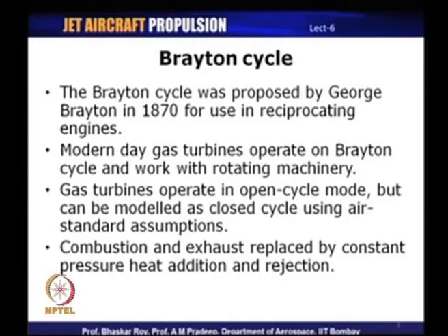That is, we assume that the combustion products can also be modeled as air, and so using that assumption we can still continue to use the Brayton cycle analysis for gas turbine engines, even though the gas turbine engines operate in an open cycle mode.